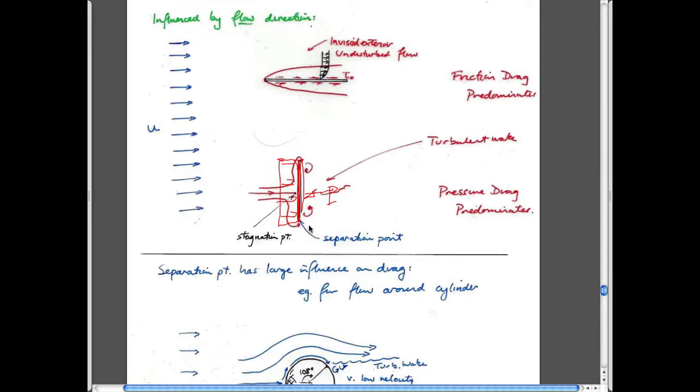If you take that plate, or if maybe you have me lying down and then having something flow over the top of me, as if I'm dead on a mortuary slab, then the forces are going to be different, and they're for a different reason. The forces would be because there's some kind of shear applied along the length of my body, because the velocity where it sticks onto this surface is zero, and as you get progressively further away from the surface, it's actually at the far field velocity u.